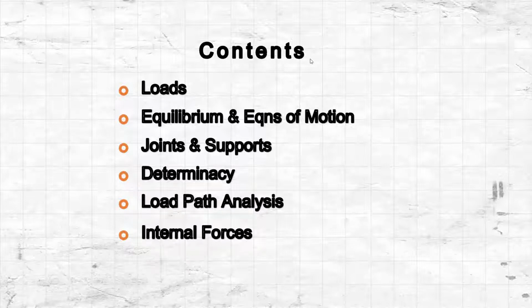For example, in terms of joints and supports, we'll have examples that are more like 3D supports, for the bearings, for example. Because I really believe that when we need to determine the radial loads and the thrust load for the bearings, what we need is the three-dimensional analysis, rather than just simply doing simple supports like pin and roller supports. So that's why it's really necessary to go through this 3D analysis.